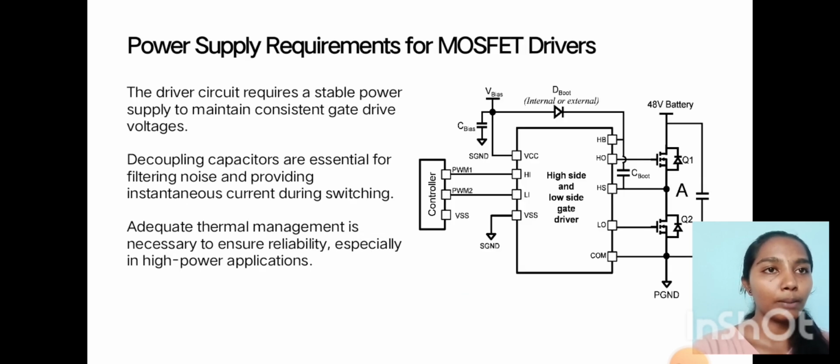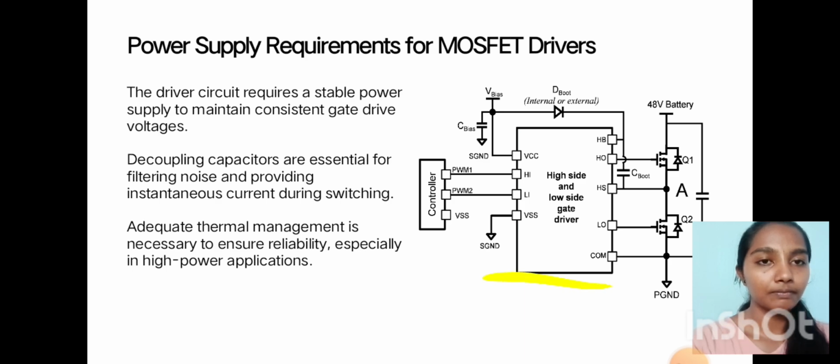Power supply requirements for MOSFET drivers. The driver circuit requires a stable power supply to maintain consistent gate drive voltages. Decoupling capacitors are essential for filtering noise and providing instantaneous current during switching. Adequate thermal management is necessary to ensure reliability, especially in high power applications.